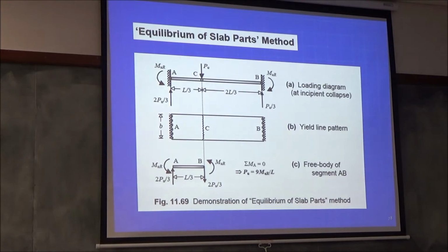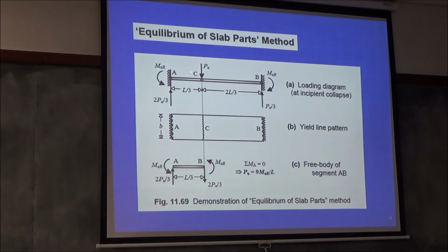external loads. So, for example, in a beam or a one-way slab, we've done this before. You take this part, L by 3. In limit analysis, we've done that, and then you can. You know exactly where the hinge is going to form, and you just did equilibrium. You didn't look at the deflected shape. You understand it? Here you only look at equilibrium. Whereas here you are taking work, that means you're multiplying the load by the deformation. Here there's no deformation. Clear?